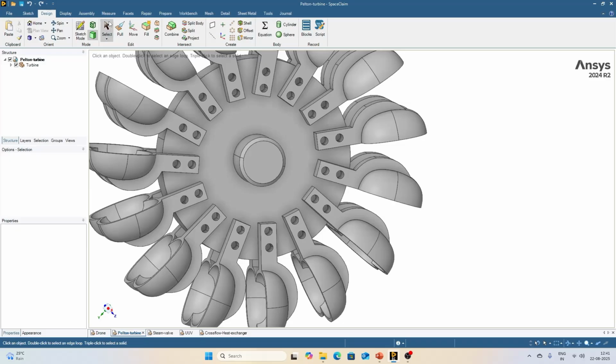The next selection mode is paint, using paint. When you click on this mode, you can see a paintbrush alongside the arrow. It's very easy to use this tool. Just imagine as if we paint these faces. Click and hold the left click on any face. Remember not to release the left click yet. Now drag or move the cursor to the faces you want to select.